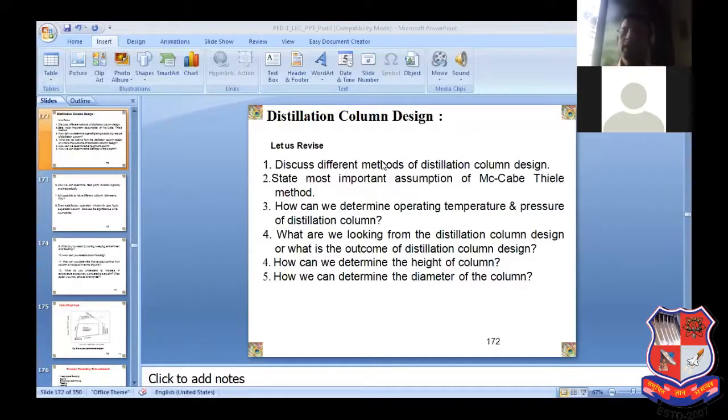So that's why you are going to face a lot of problems in operation of a distillation column in terms of your improper condenser. Condenser cannot take the load of the vapor, and that's why you're not able to get the required liquefaction. So in that situation, what is going to happen if you replace water?